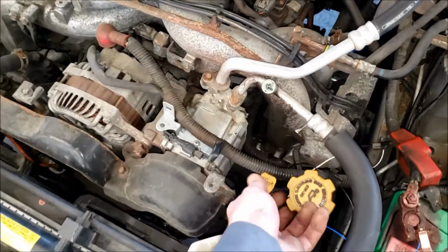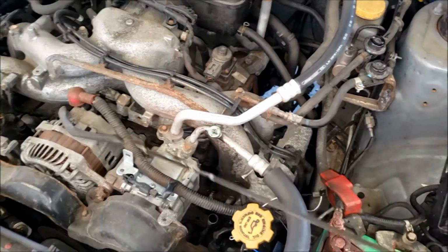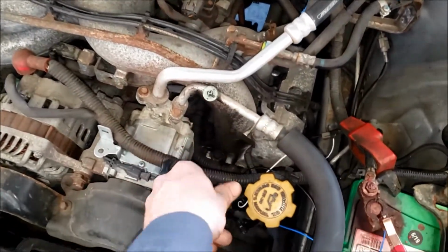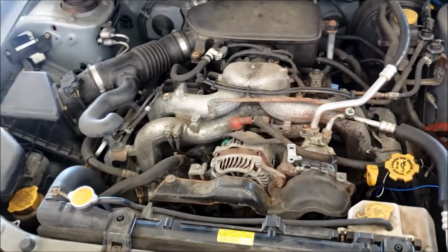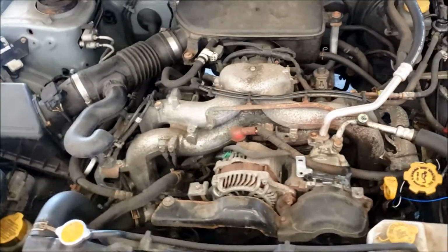Next thing you're going to want to check is your engine oil level. Make sure it's clean and up to level. And if it's been 10,000 miles since your last oil change and it's not on the dipstick, you might want to start by just doing an oil change and clearing out the code, because that can definitely cause trouble codes with the VVT systems on these.